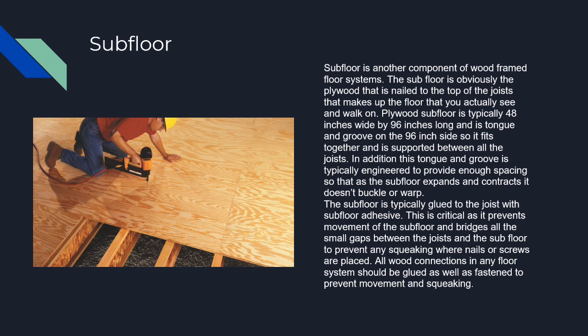The subfloor is typically glued to the joist with subfloor adhesive. This is critical as it prevents movement of the subfloor and bridges all the small gaps between the joists and the subfloor to prevent any squeaking where nails or screws are placed. All wood connections in any floor system should be glued as well as fastened to prevent movement and squeaking.